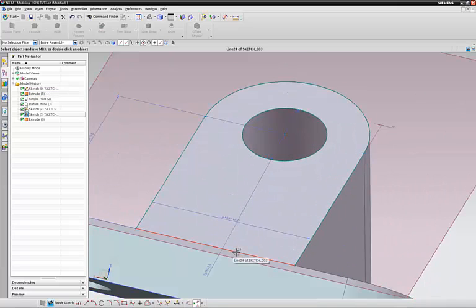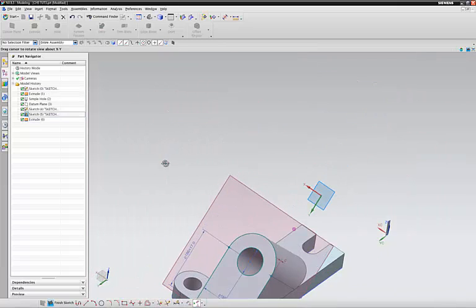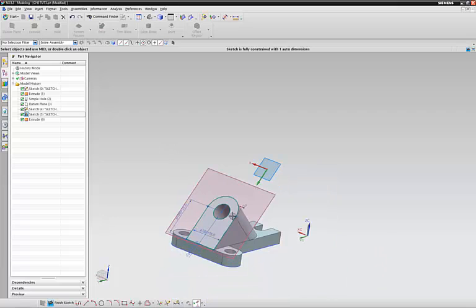You have to be careful right here. Sometimes if you input a line yourself, it'll create errors later. NX is supposed to be able to automatically generate the reference for this location right here, and so it'll automatically enclose the solid, so it can create something.